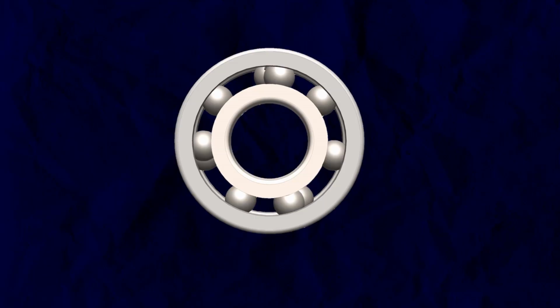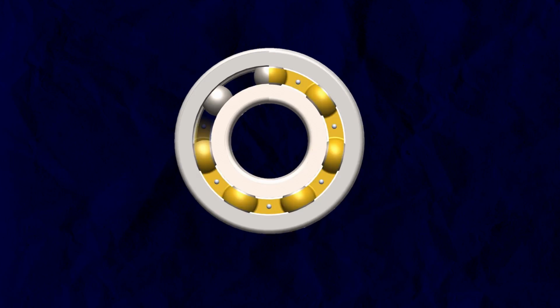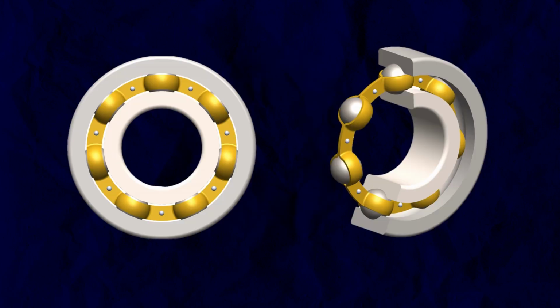The problem is these balls will collide with each other and make friction at high speed. Also, if the balls are not equally distributed, the load will also not be evenly distributed all around the bearing, and it will reduce the bearing life. So to keep the balls equally distributed, we have to use a cage, something like this. And this cage also rotates with the balls. So this cage has to be light in weight.